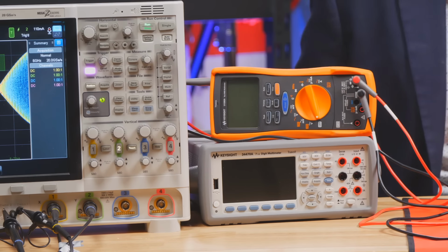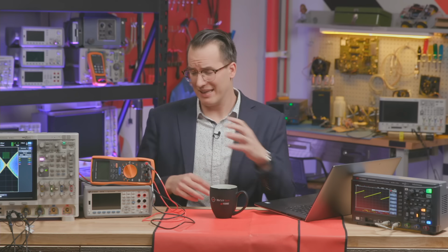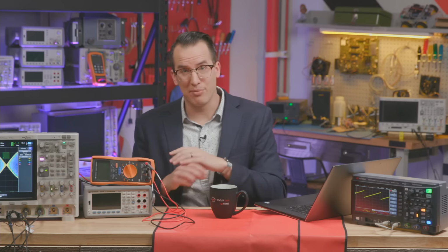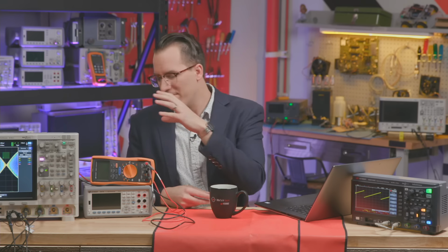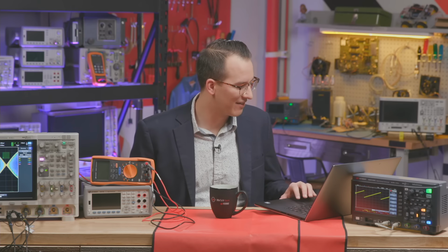So that's really where it comes down to it. One of the interesting things we see people do with especially the higher digit DMMs is they'll get this calibrated and then they'll calibrate all their other meters that are lower digits, so they're 6.5, 5.5, 4.5, based on the calibration of the 7.5 digit, because you have enough extra headroom to get the measurements you need on those DMMs. So that's a good question. We should do a video on that one. I'll add that to the list.